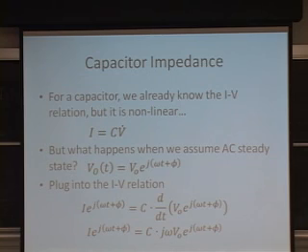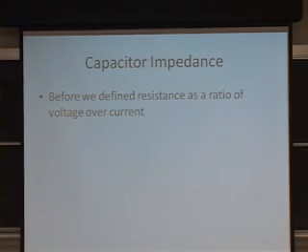Okay. First, we plug this in, and we assume that the current is going to take the same form as the voltage. The voltage is oscillating up and down. You can bet that the current is also going to be oscillating up and down. You can observe this on a scope or anything that you really want. So if we plug in our complex exponential for voltage and take the time derivative, for a complex exponential, we get a j omega that comes out here. And we have these complex exponentials on each side, so we can cancel them.